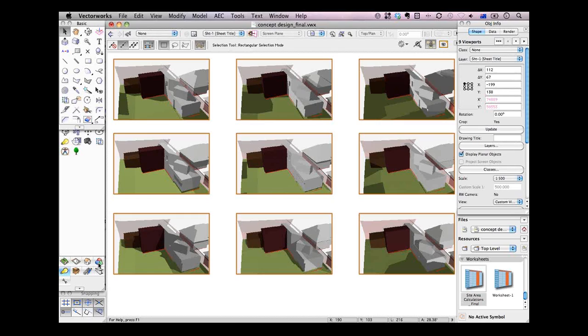You might notice that I've got quite an unusual modern design for my building. It's got holes, it's got different blocks of different heights, and I'll cut bits off, so I use the split tool, I use the push-pull tool, and I've got those boundary setbacks so that I know that my building complies with those boundary setbacks. At this stage, and this took me a couple of hours to get to this point, you know that you're complying with the building regulations, the areas, setbacks and volumes and building heights and sun, and I think it's really powerful. It gives you a lot of information to go really quickly.